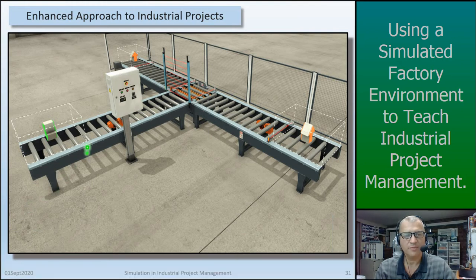So in this case, we have an emitter here, and this is used to drop pallets onto the conveyor automatically. The conveyor and motor move the box and pallet along the conveyor to this set of sensors here. And this set of sensors detects the height of the box that's sitting on top of the pallets. Then the pallet moves on to this lift and divert mechanism here, which can shuttle the parts left or right depending on the size. There's a sensor that detects that the pallet is in place on the diverter.